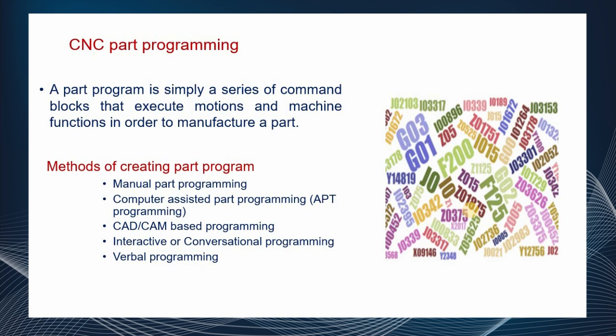There are various methods of creating part programs, such as manual part programming, computer assisted part programming, which includes APT programming, CAD/CAM based programming, interactive or conversational programming, and verbal programming.